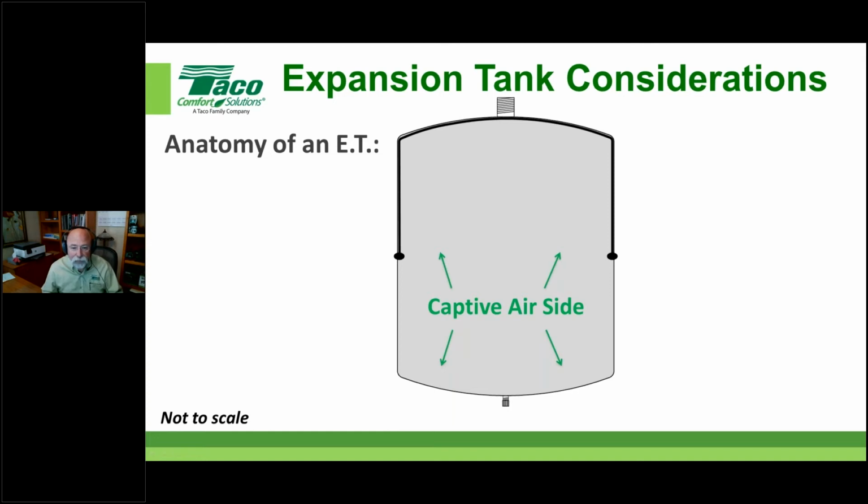As long as the Schrader valve's not leaking, and as long as we don't have any leaks here where the seals are, this diaphragm actually attaches, and that air is going to stay captive inside that tank. So that's our captive air side.